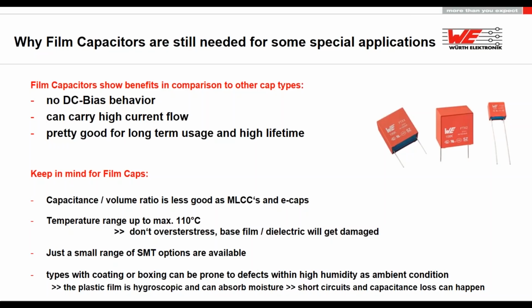And what they're also very good at, let's say they're in between the E-caps and MLCCs, is long-term usage and lifetime expectancy, because if you run a film cap in good conditions, you can really get a long-term running product. If you do not have too strong humidity and the encapsulation is fine, a film cap can run pretty fine for a very long time. Really keep in mind the temperature.